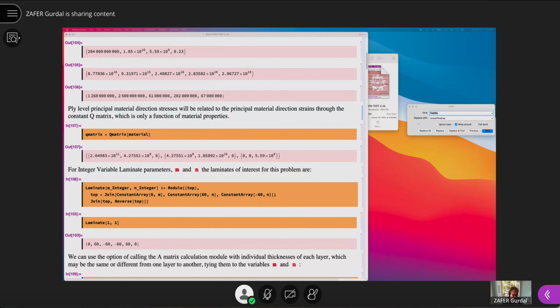Unless you're a graduate student really working on this particular topic of designing a composite part, we don't normally get into those. When you get into those, you may require different layups in different parts of the structure. This is called dividing your structure into subsections and designing those subsections separately. And then you try to blend those designs to one another, because nobody designs one layup here, another layup here, and puts them side by side.